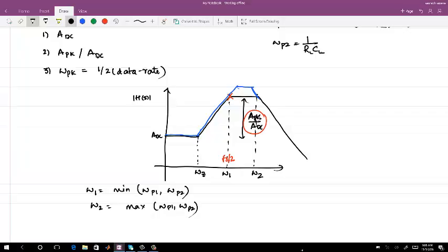Okay, if you do that, then you will be trading off in terms of power. So putting an equation that d by d omega of mod of H(s) at the omega peak frequency, the frequency which I want, should be equal to 0, ensures that it is the only local maxima in the system. So I do not want more peaking at a higher frequency. It may turn out that it is better for your equalization, but it is also about how much power you spend in doing all that. If you are getting it for free, it is good, but normally you do not get anything for free. Okay.